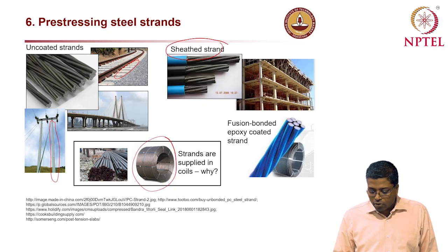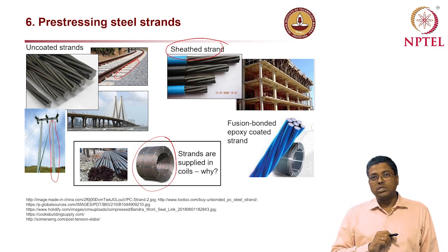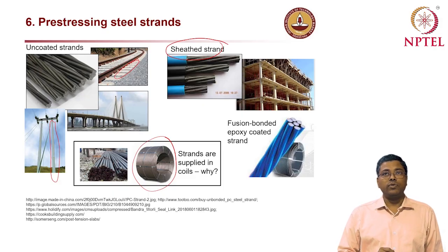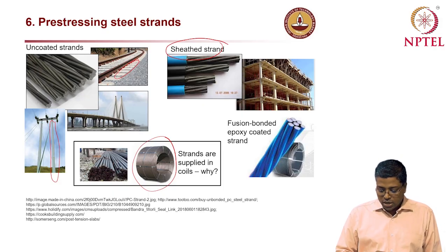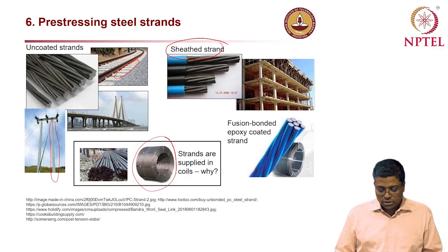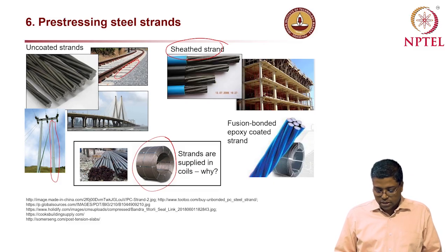When you talk about high-rise buildings with post-tension slabs, they use these mono strands very much, because you don't want to bunch a lot of strands, which will lead to significant bursting stress. So they distribute the positioning of these strands, for which mono strands are used.